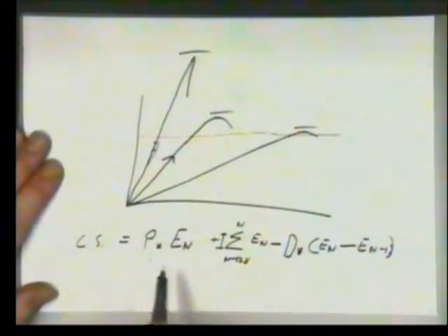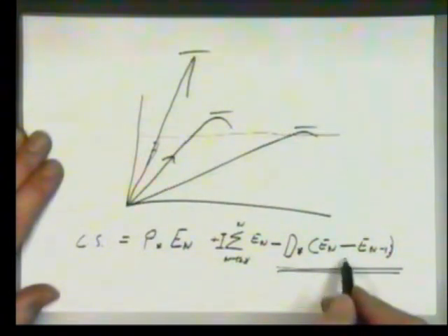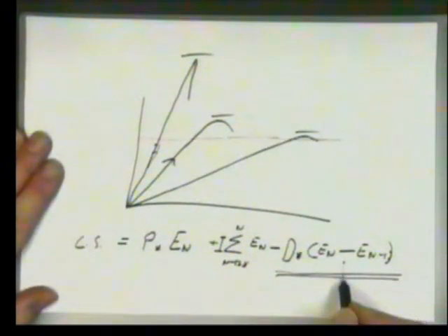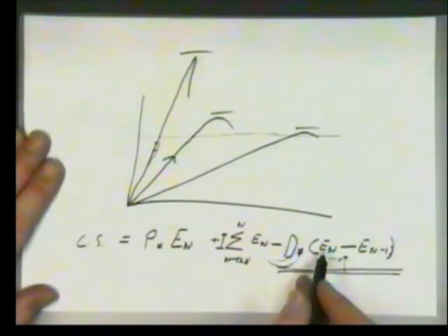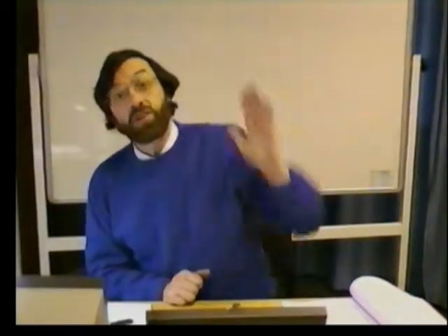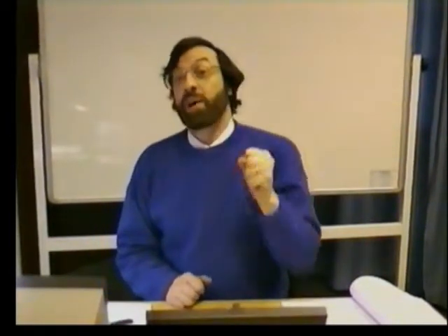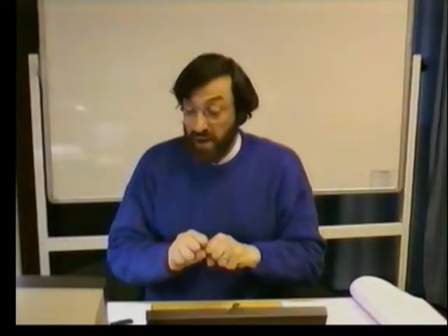the control signal. So what we have is a proportional term, an integrator, and a derivative term. And what the derivative term is doing is saying if we're running away, if the rate of change is too great, we start slowing down the system. We put the brakes on. The derivative term, also known as the damping term. If we're going too fast, it slows us down. It says, oh, just hold on, wait, slow down. You're going too fast. You're going to cause trouble in the future. Let's stop you causing trouble in the future. We'll slow you down now.